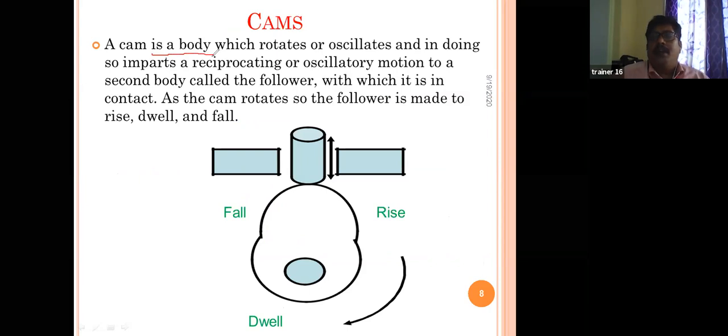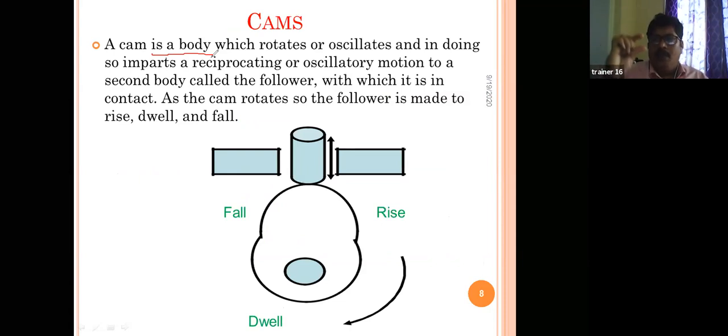I think all of you know that a cam rotates automatically. You know very well, you've seen IC engines, the inlet valve is moving and the outlet valve is moving, right? So these linear motions are moving with the help of the cam rotation. If you see clearly here, in this portion, this lever rises up, and this is nothing but a dwell.